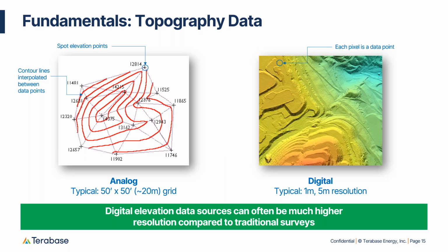When you request a survey, you're probably going to specify the contour interval. The survey that you receive back from a licensed surveyor should be accurate to half of whatever the contour interval is. So if it's a 1 foot contour, the surveyor is going to state that it's accurate to half that, or 6 inches.